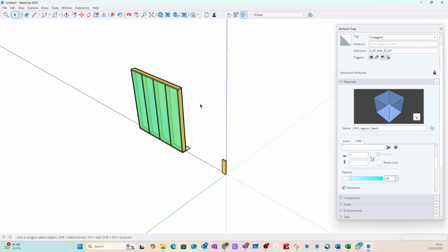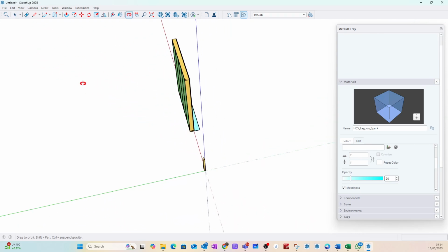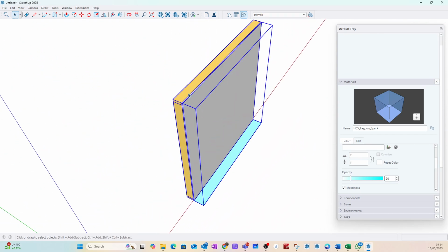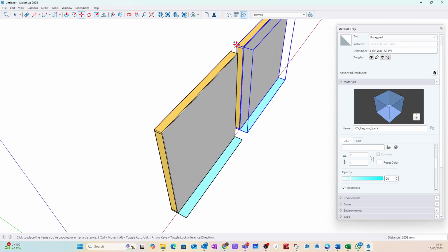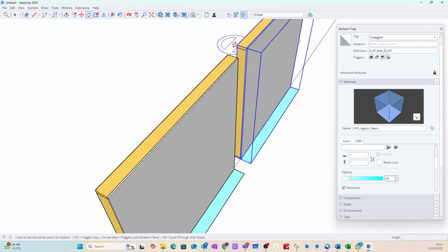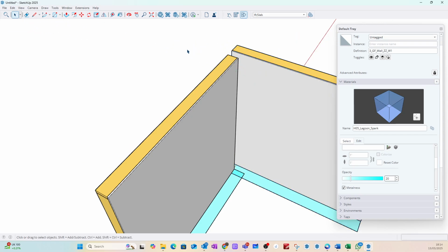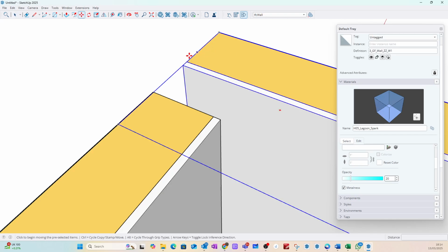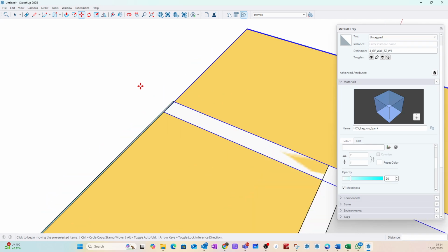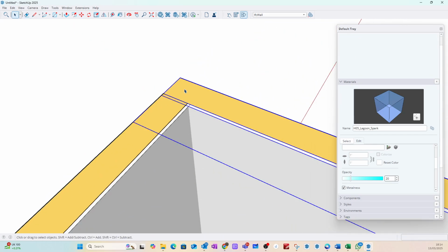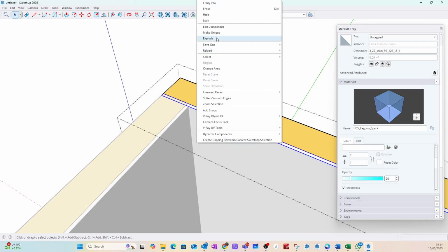Press create. Absolutely amazing. We'll select that, now give this an IFC. This will be an IFC wall. There we are, IFC wall. Excellent. Now what we could do is select the wall and duplicate it across. We'll rotate it. We've done this in class the other day as well, so we'll do it here. And what I'll do is we'll tidy this up. We'll do it like that. And then we'll select the wall, make it unique. Select that plasterboard, make that unique.